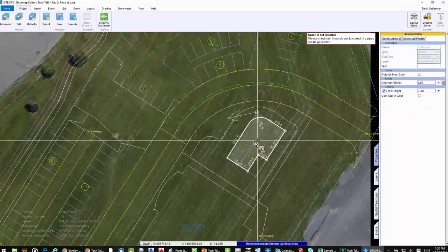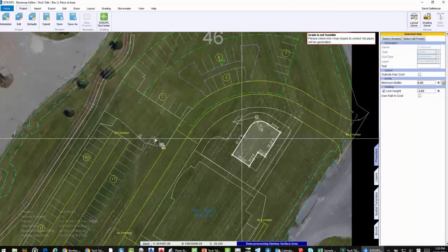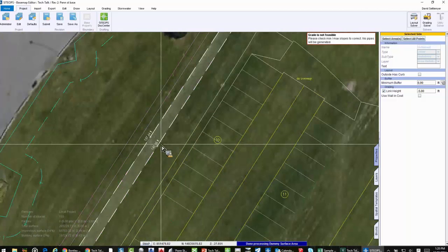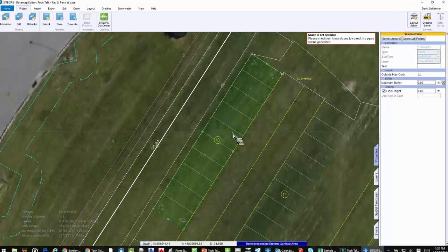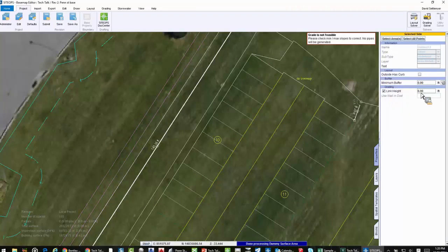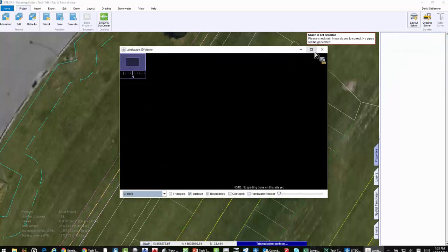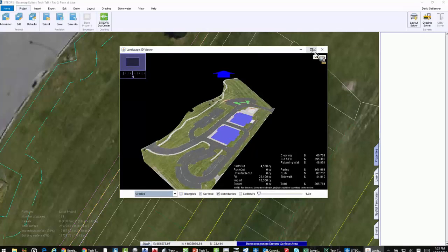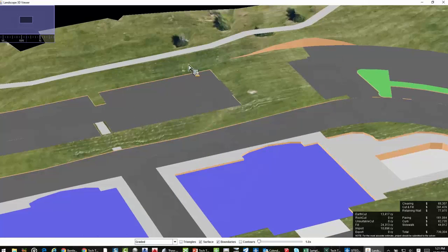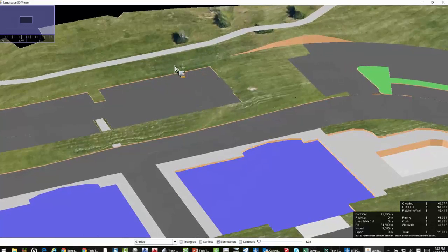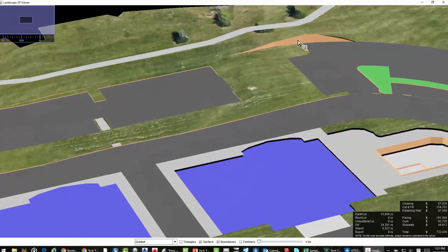But let's say I'm over here by that steeper hill, and I've got a sidewalk going up for the bicyclist. I can also come in, and what you can see right here is, notice how I have this link height set to 0, and I'm going to show you what happens. Again, I'm telling it no wall. 0 means I want you to tie in exactly as you're supposed to. It's almost like don't even think about it. And you're going to see it, I've told it right up along that area, do not have a wall. And over here on the right, just so you can see the difference, I left a wall.